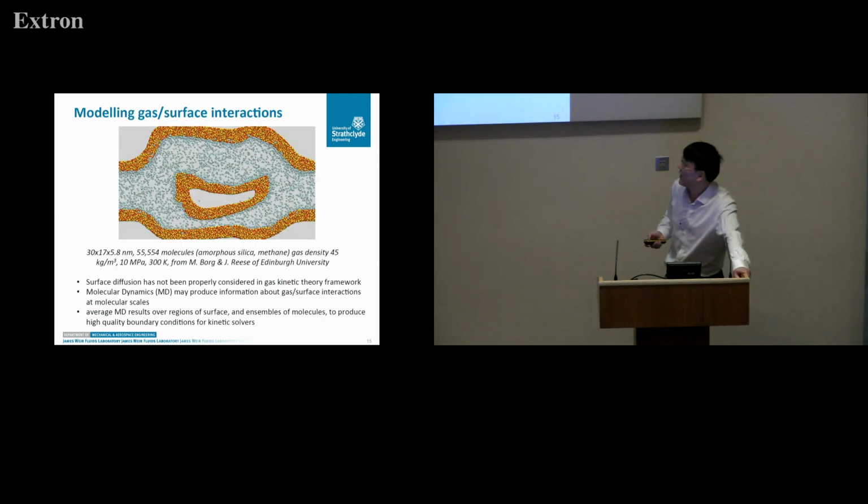We are also now working on how we can use molecular dynamics data and plug it into the gas kinetic solver, which can provide us with proper boundary conditions. We apply mean field theory to model the attraction force between the surface molecules and the gas molecules, and apply a hard sphere model for the repulsive force.